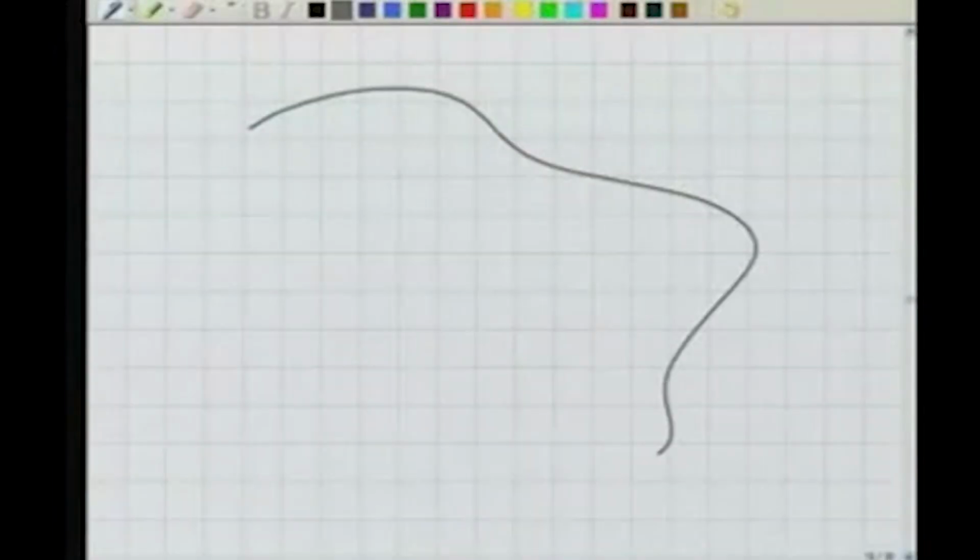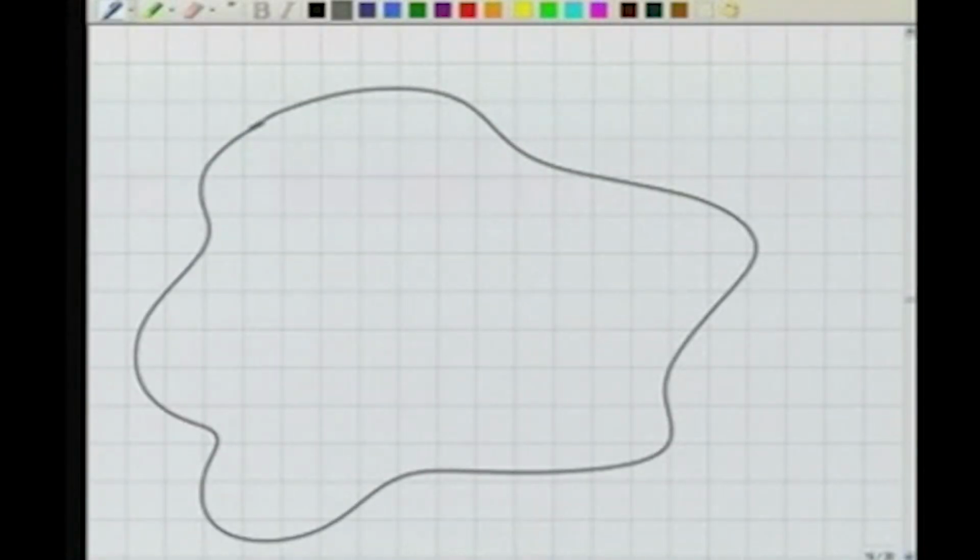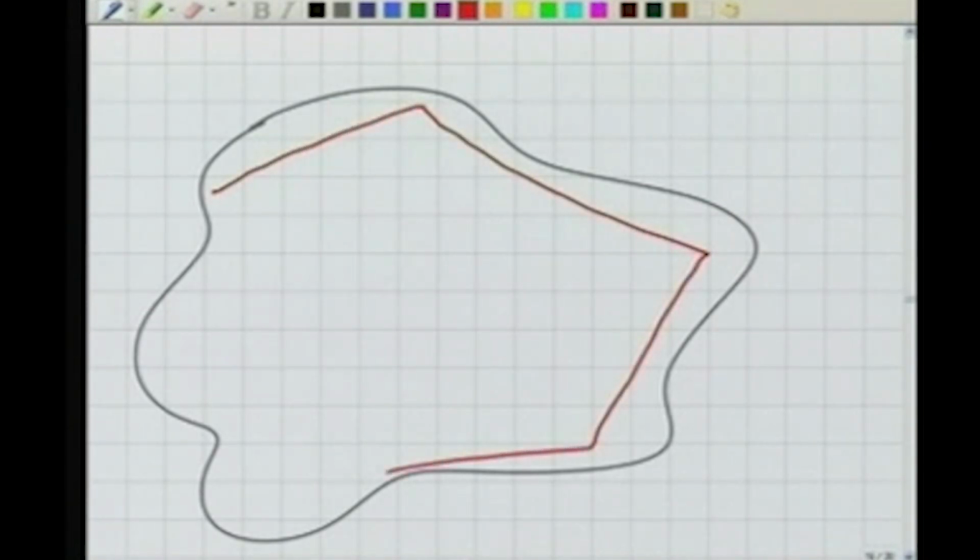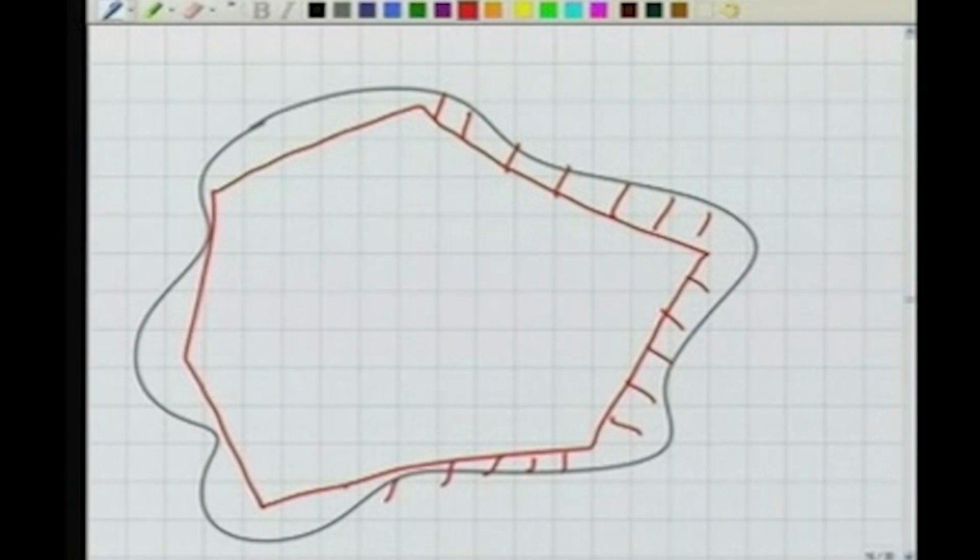But in some other circumstances, for example, in a garden, that's a garden. For this garden, we need to find its area. We have to determine the area of the garden. What I will do is go for a traverse all along the boundary here and close it. Then I take all these offsets. So by measuring the offsets and by measuring these angles and these lengths,